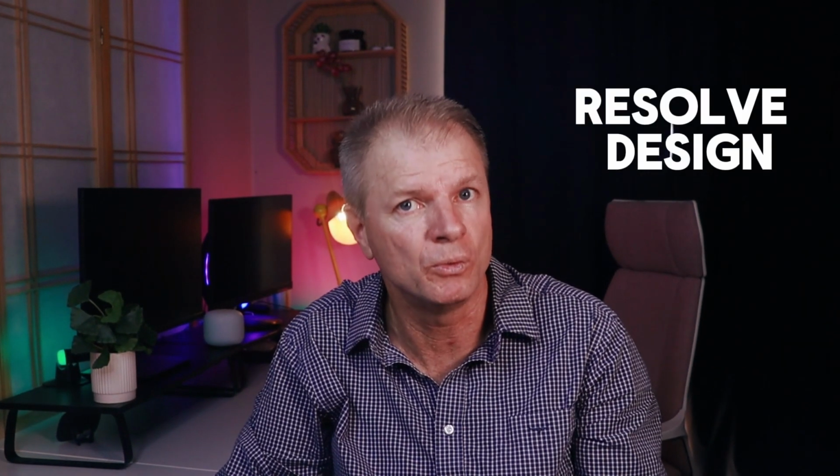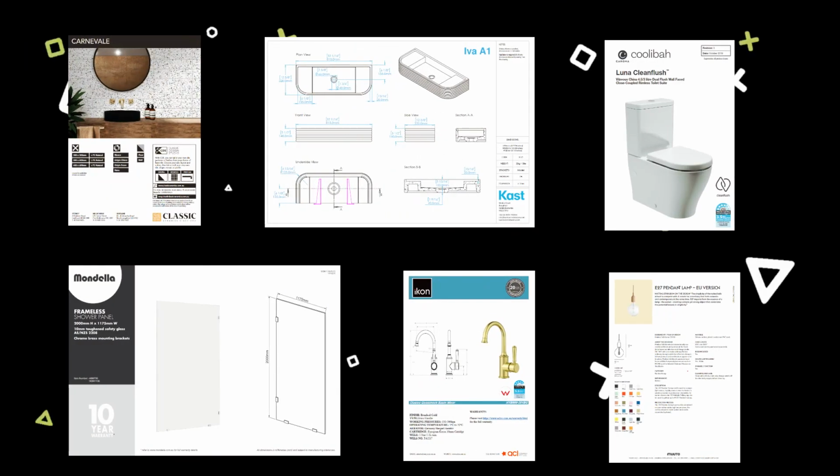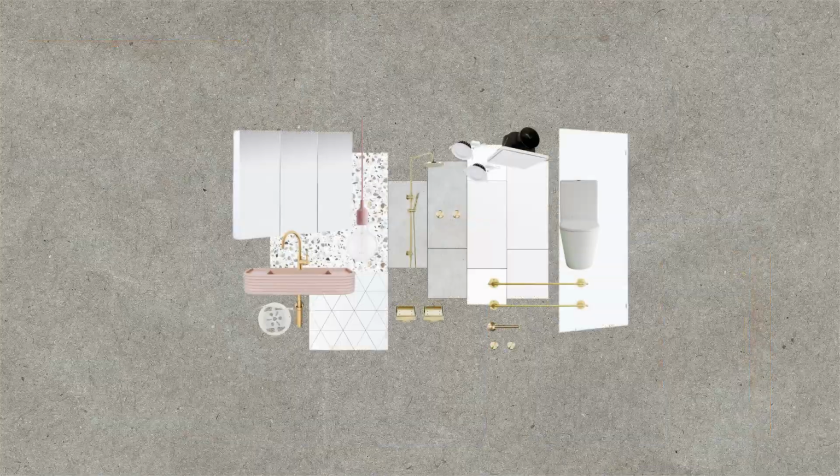waterproofing membrane. So the entire process is lengthy, and in order to achieve a high quality outcome at a reasonable price, the design first needs to be resolved with good amount of detail, including the selections and scheduling of all the vanities, cabinets, tiles and fixtures. Now be sure to download all the data and specification sheets for everything that you've selected. Then you are ready to approach 2 or 3 contractors, share the sketch plan, the mood board, the bill of quantities and the spec sheets, and indicate what items you will supply so the contractor knows to supply everything else. If you follow this guide, you will receive 2 or 3 comparable quotes, allowing you to move forward with confidence.